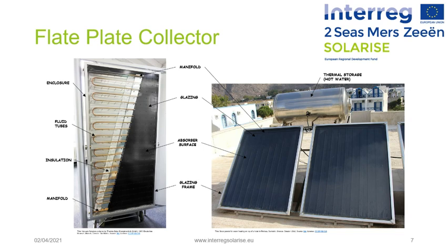Many geometrical arrangements for the fluid tubes are possible, but the header and riser collector is the typical design for flat plate collectors. The underside of the absorber plate and the two sides are well insulated to reduce conduction losses. The transparent cover is used to reduce convection losses from the absorber plate through the restraint of the stagnant air layers between the absorber plate and the glass.